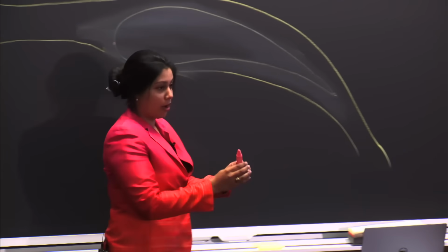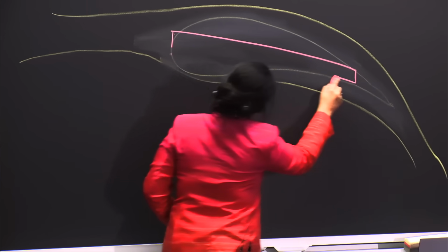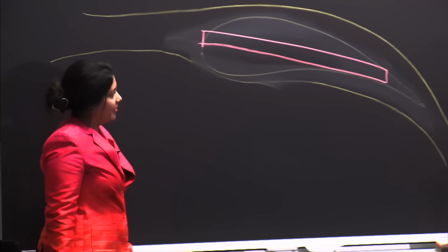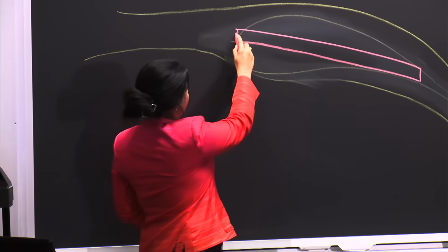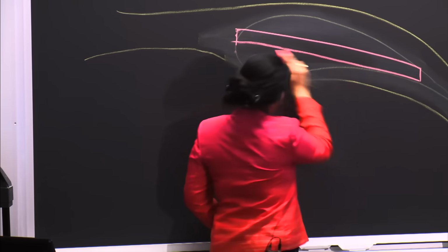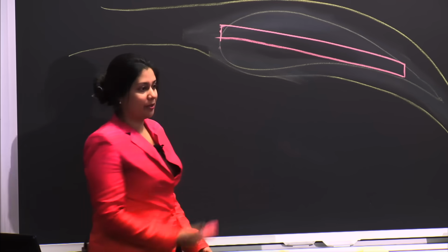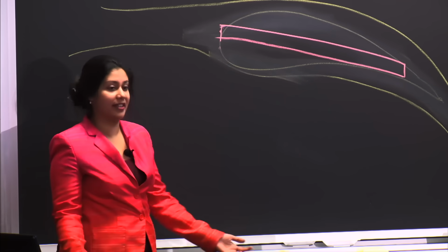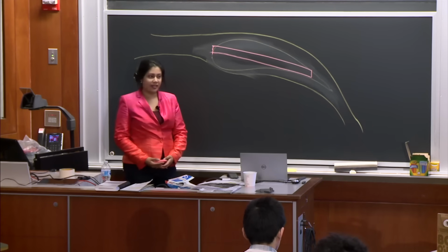we're going to use red for wrong, okay? It's like a little rectangle, right? That's what a paper airplane's cross-section of its wing looks like. Well, surprise, surprise, as you said, it's the same at the top and the bottom. So the distance that an air molecule would have to travel over the top and the bottom is identical. So really, the equal transit theory completely falls apart.